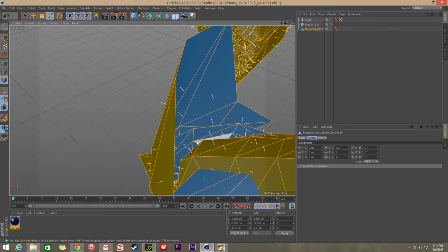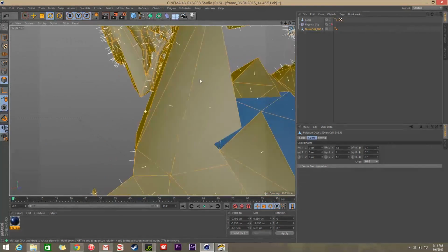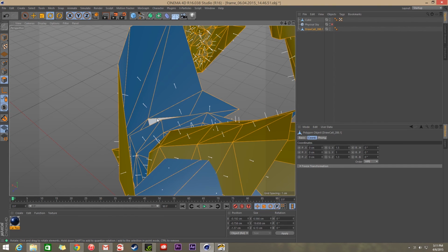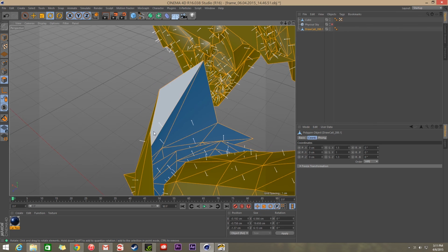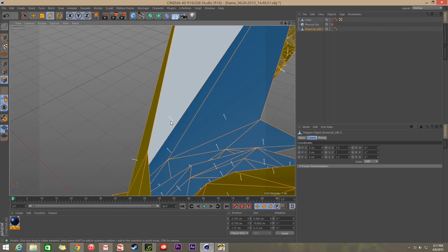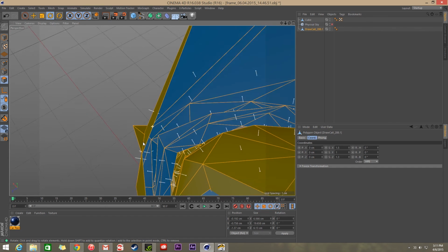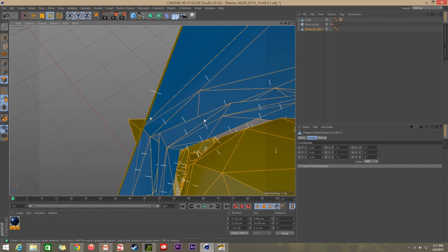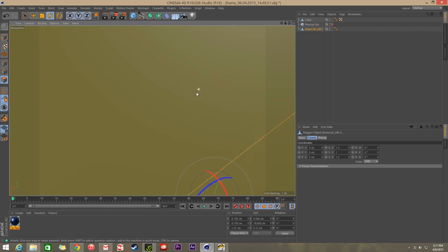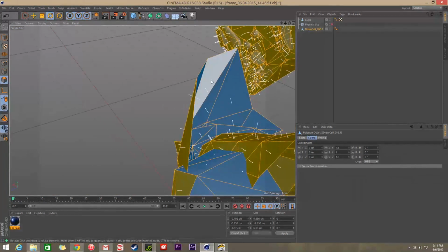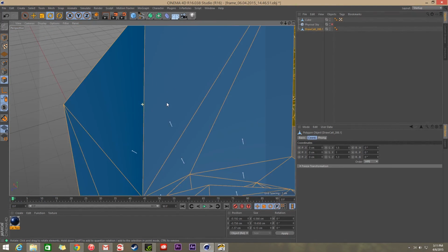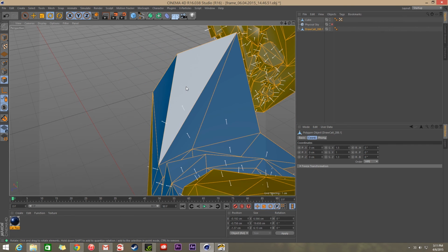And as far as the program would actually read this file, it would consider this as having no depth, because as far as the computer is concerned, this polygon has no depth. It's thinner than a piece of paper. It just doesn't exist. It's so tiny, so thin. So the way we'd have to fix that is because a printer couldn't print anything this thin that has no depth, because in the real world everything has depth. Even paper has a certain depth to it.